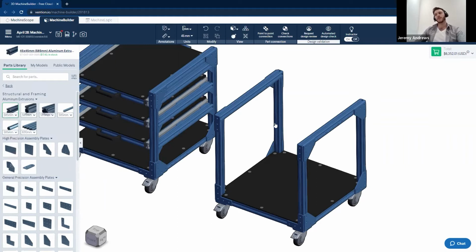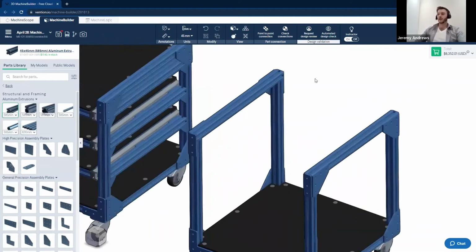So there's a few step process. For example, you'd have to then measure the internal dimension, figure out which one you need, go to the drop-down menu, select the precise one that you need, bring it in, and attach it. Again, it's still a little bit faster than standard design softwares, but it can be even faster. And this is where I'll highlight the shortcut, which is the letter I, or the insert key on your keyboard, that allows you to reinsert the last clicked part or the last inserted part in your design. So with this, I know I'll be using a 45 by 45 millimeter extrusion. So I can simply select one in my design and press I to snap it to the edge of my cursor.